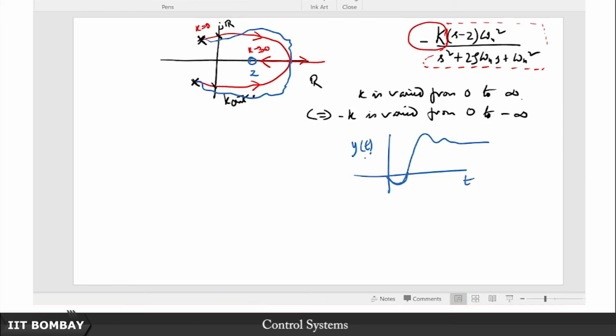The lesson is that you will encounter these non-minimum phase systems in practice, such as canard controlled aircraft, and because it is a mechanical design, you will have no option but to deal with such systems and then consider this complementary root locus. Hence it is good to be aware of how to sketch the complementary root locus side by side with the conventional root locus.